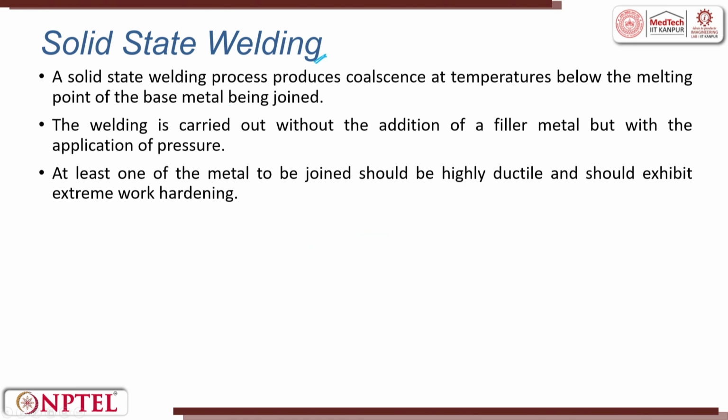The next classification of welding process is solid state welding. A solid state welding process produces coalescence at temperatures below the melting point of the base metal being joined. The welding is carried out without addition of a filler material, but with the application of pressure. At least one of the materials should be highly ductile and should not exhibit extreme work hardening behavior.